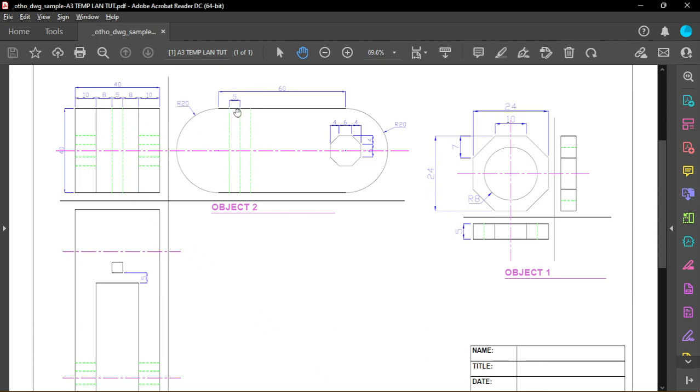Okay, now let's start with this. We have this part for the square hole, then we have this line for this separation, the one that makes the interior groove. The square hole is at 25 from this edge. The circular part to the hole, that distance is 25. Then after the hole, we have a distance of 5.